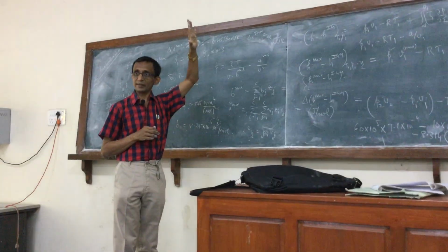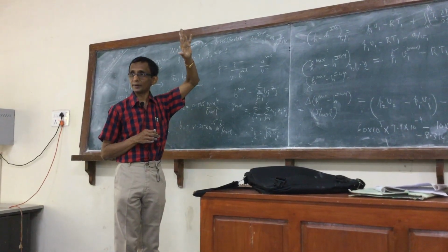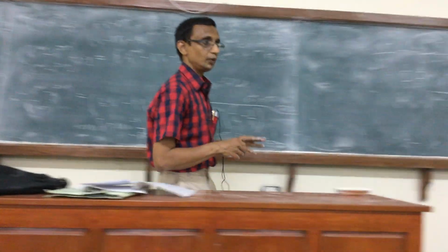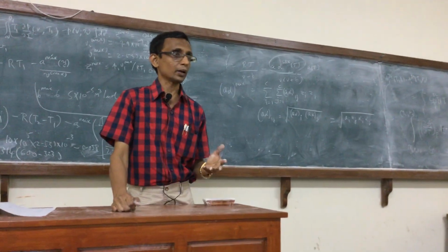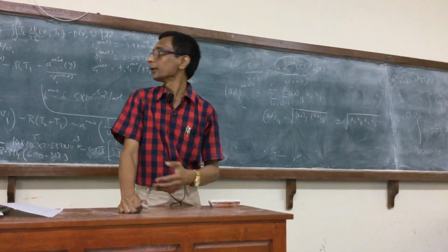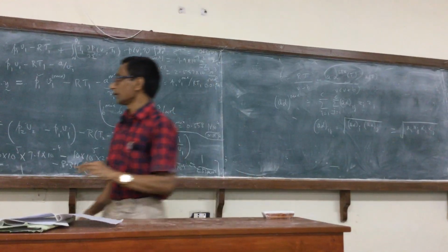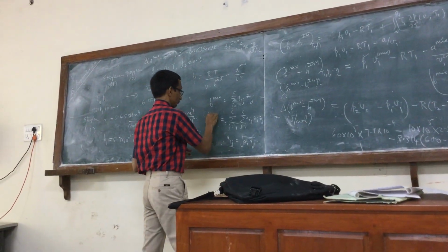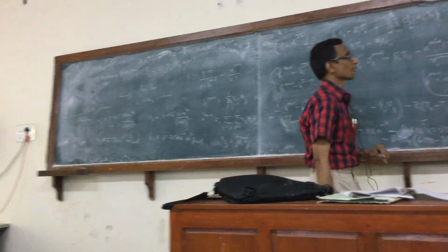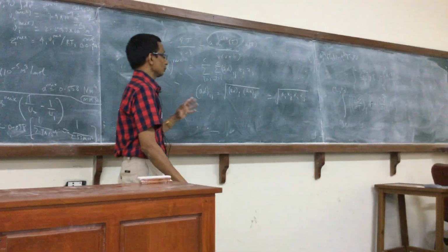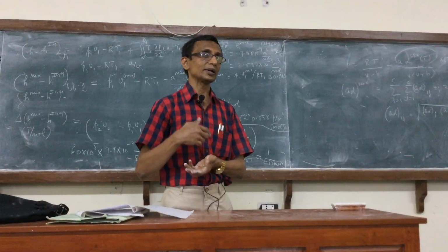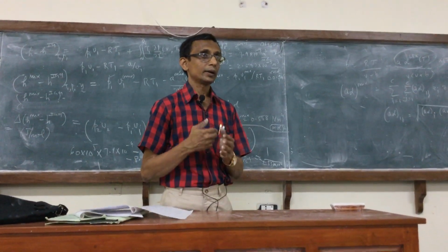So I have to go to the Peng-Robinson parameters, B parameter, or SRK parameters. So when there is a different set of parameters in terms of Pc, Tc and so on, calculate the individual values for ethylene and propylene, Peng-Robinson or SRK. Then I need to calculate the A mix. For us actually it is A alpha mix here. So obviously the same formula would apply. So now, the parameter calculation itself will depend on temperature.